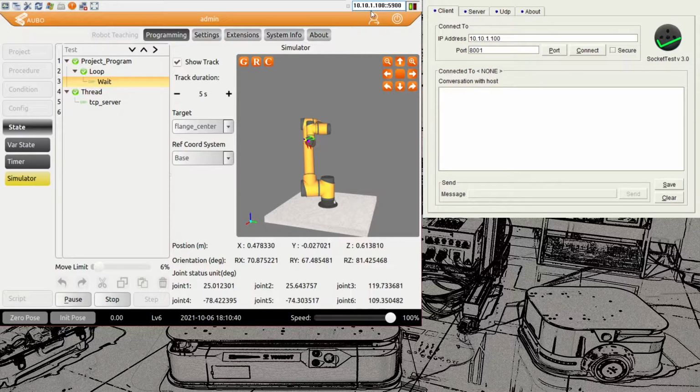Here, in the robot window on the left, on top of a bar there is the IP address the robot is using in server mode, and on the right side is the client on a notebook. That's why we are running in client mode, and it needs to connect to the robot under that IP address. And remember, we defined port 8001 for the connection on the robot. So if our script is running right now on the robot side, our socket test is ready to go.